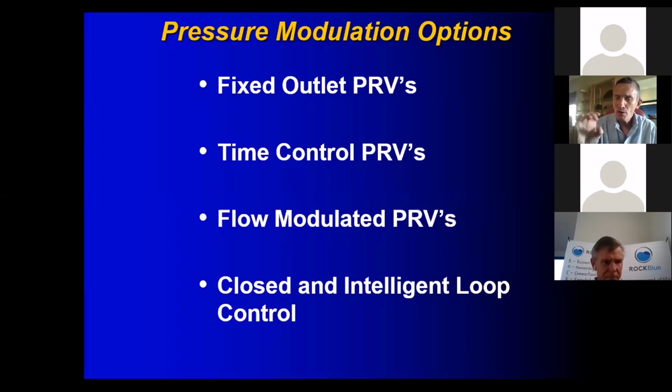Now, the problem with that is, once you've designed a zone for that, most of the time your zone is not operating at full capacity, which means the friction losses are not at their maximum. They're actually somewhere between maximum and minimum, which means the pressure at your critical point most of the time is then above the 25 meters of pressure.